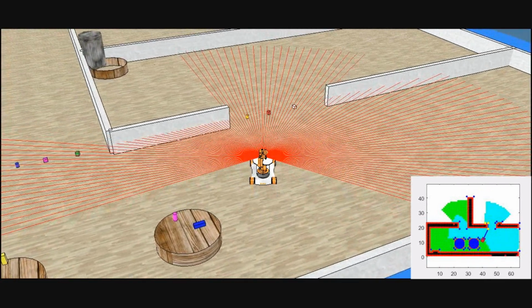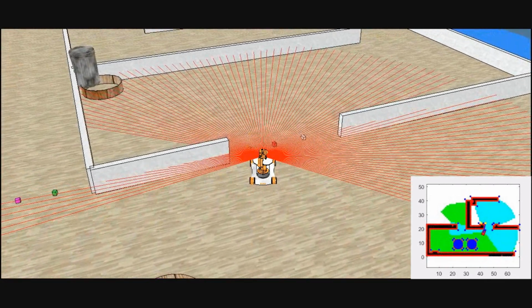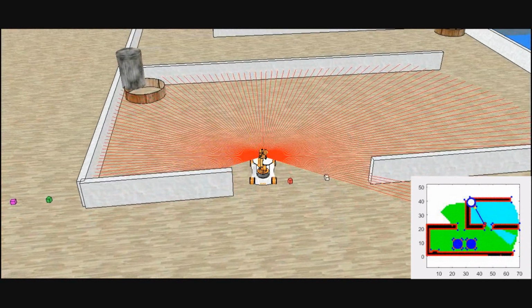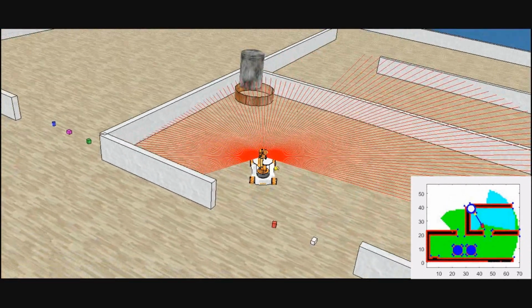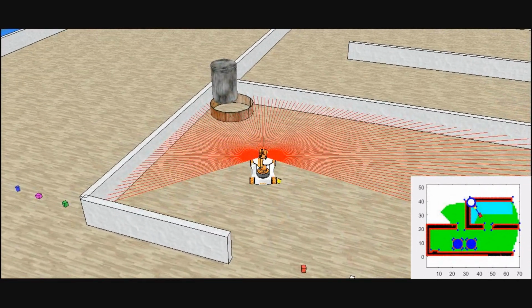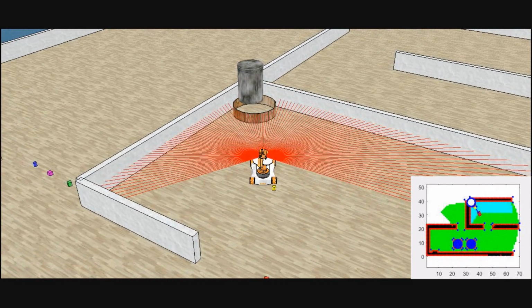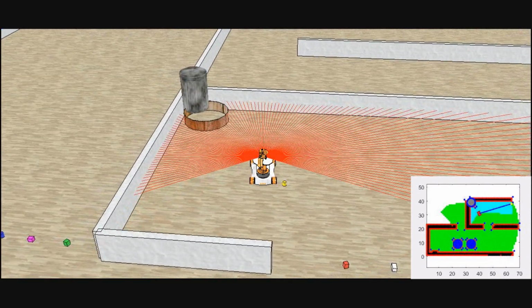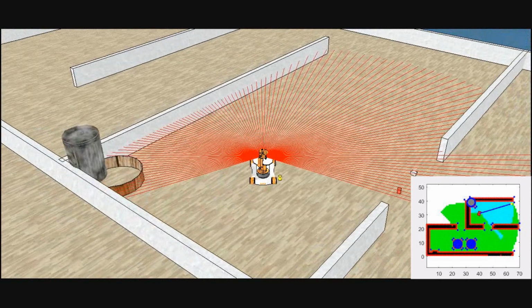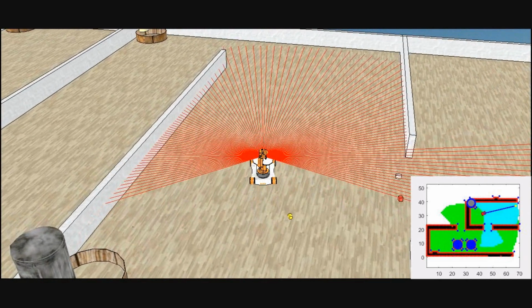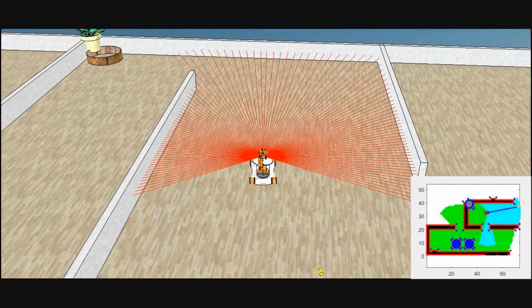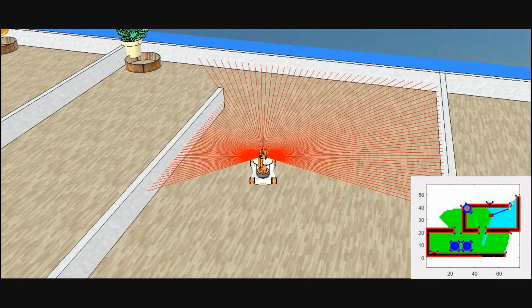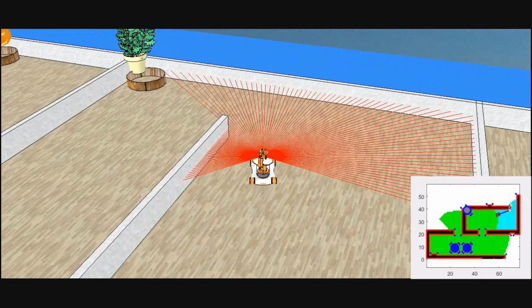To do so, we try to identify the closest unexplored point from the latest identified point. To compute a path from youBot's position to an unexplored point, we compute the edges of each obstacle and use Dijkstra's algorithm from those edges to find the shortest path. These edges are depicted by blue dots around the obstacles.